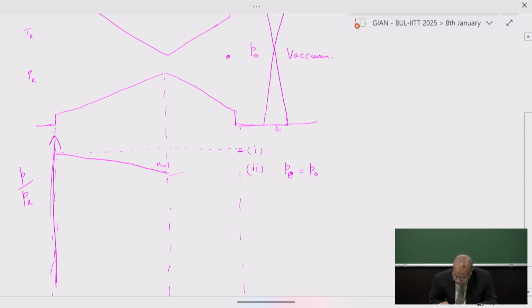Still subsonic flow. So the pressure increases in the divergent part. Now we will repeat this one. We will open the valve further. The ambient pressure decreases further, and that is also equivalent to the exit pressure. Now the gradient is becoming a bit more. The flow starts to accelerate even much faster.